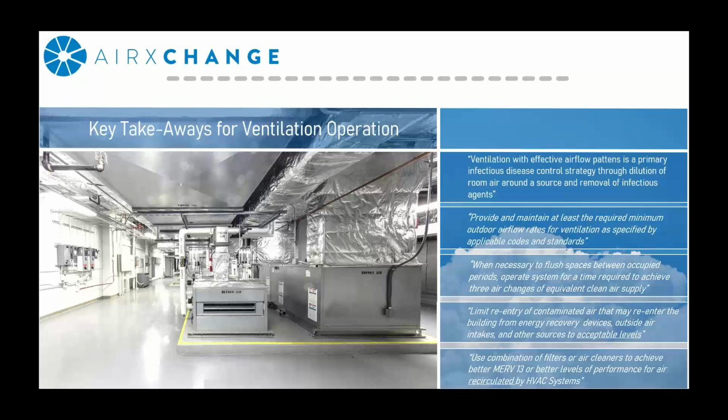Limit re-entry of contaminated air that may re-enter the building. This includes recirculation from energy recovery devices. So I'm going to speak more to this in a few slides. And use a combination of filters or air cleaners to achieve MERV 13 or better for air recirculated by HVAC systems. Now, I highlighted recirculated air here because it requires an understanding of how air gets recirculated in the occupied space. And I'm going to talk about that in more depth in a couple of slides.